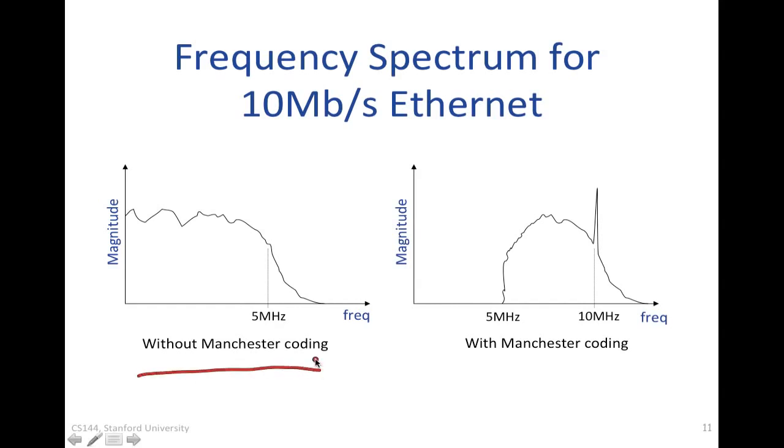We would see at different frequencies, so this frequency here is the 5 megahertz, which is the average when I've got a sequence of zeros and ones, but a random sequence of zeros and ones. I would see some frequency component around here, but it's not strong enough to find it and lock onto it and know that that was the frequency of the clock.